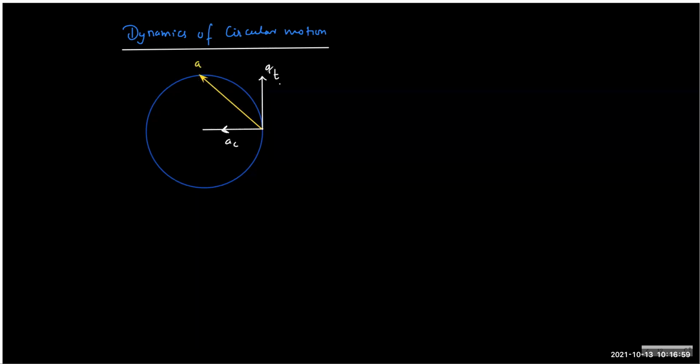So for the laws of motion, there are three ways of writing. You can write net force is mass into total acceleration. You just add all the forces and you just add m a. This is one way of solving. Or, don't write the total one, you can do it individually. What you can do is resolve the forces along the tangent and along the center.